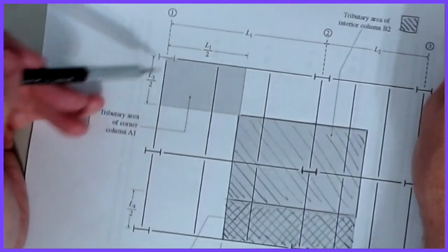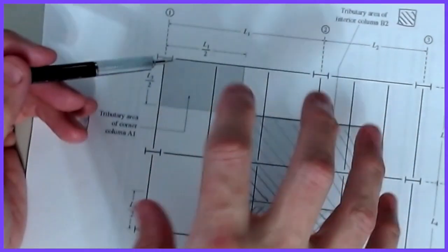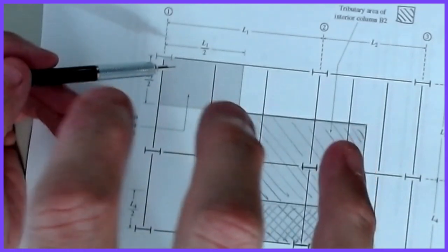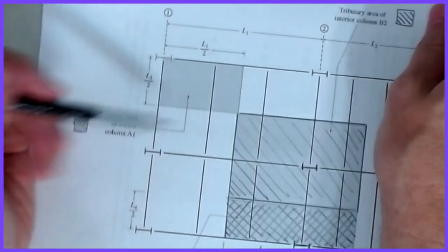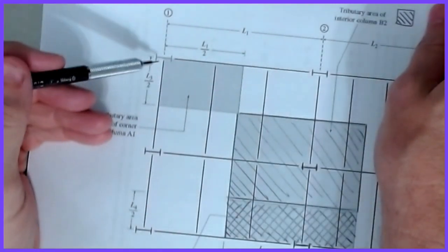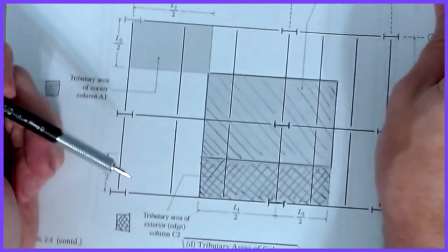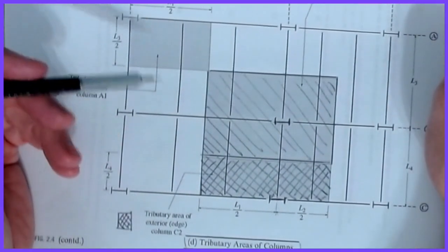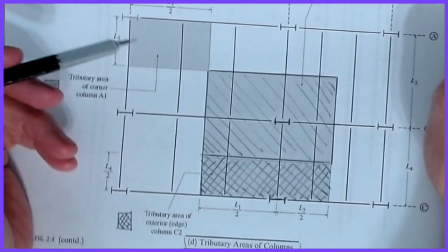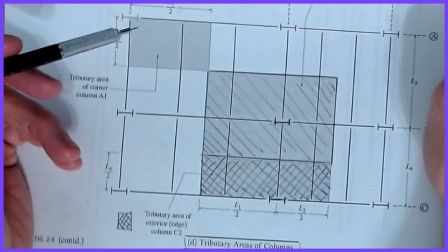And this is really handy for buildings that are multiple stories, as I can figure out the loads for this floor, and then if this framing duplicates for the next floor up, and for however many floors, I just take the values from one floor and multiply it by the number of floors above it, and I can quickly get an axial load in a column just using these basic tributary areas. So it's a little bit of a crude statics, if you will. It's mostly area methods, and it's not overly difficult, but it will get you a first guess at the values, and you can do it very quickly and very efficiently to get a sense of those.